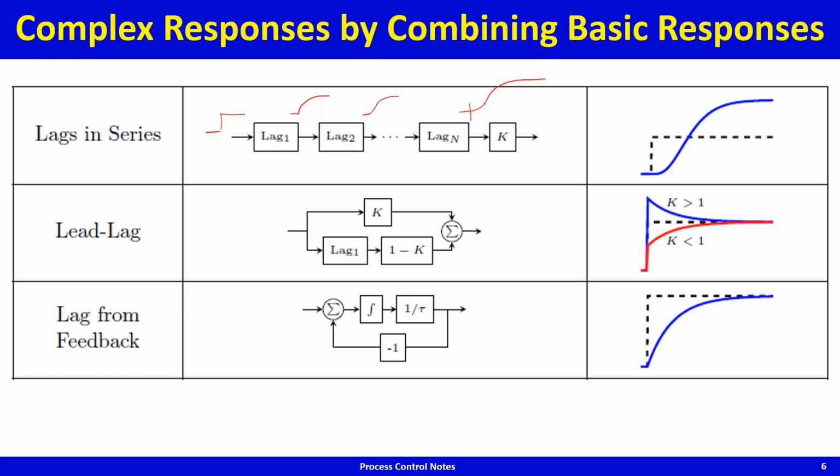not to scale. So nothing happens for some time, and then of course you multiply by the gain, and then what you get is what is drawn here. You have a step change in the process input and the process output, which is over here. Nothing seems to happen for some time, and then it slowly, sluggishly rises to a final steady state value. This slow, sluggish, S-shaped kind of response is very characteristic of many processes in nature. We see a lot of times the slow, sluggish, S-shaped response in chemical processes.